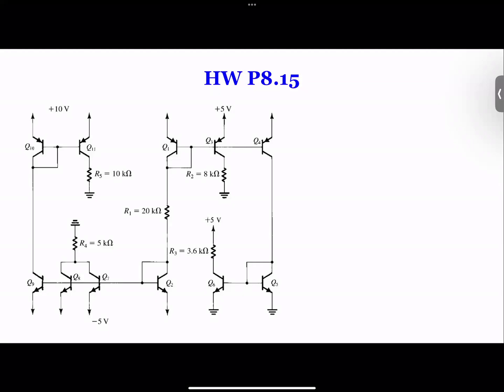And because this base is connected, in fact, if you look at this circuit over here, it does not have any amplifier. Everything is a current source, a current steering circuit. So this number one step, we identified, okay, well, there's no amplifier, fine. So this purely is a current mirror device. A second step is, well, where do we start to calculate the voltage and current? Well, we need to start to look at where we can find the voltage.